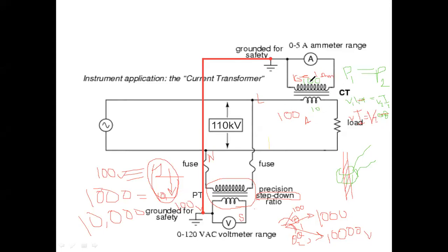And then we already know this is the ratio. 100 is showing 1 ampere, and 10 is showing 0.1 ampere, and it is easily measurable by your measuring instrument, like an MI type instrument, dynamometer type instrument, or digital instrument. Then we can easily change the scale, vice versa. If your ammeter is measuring 1 ampere, actually the transmission line is carrying 100 ampere.